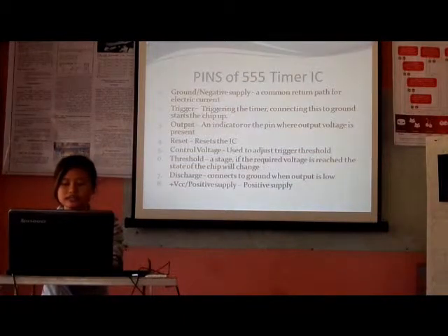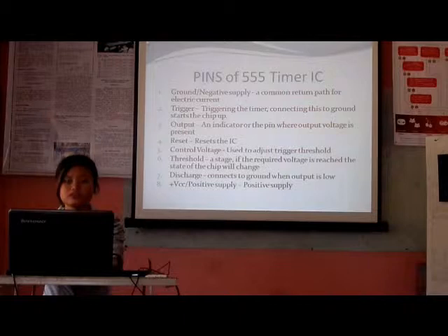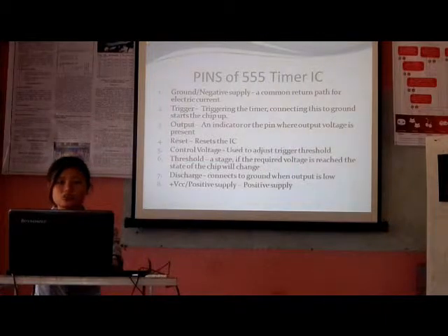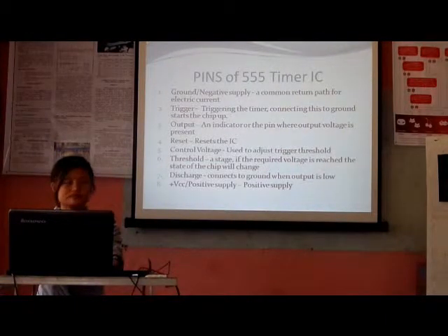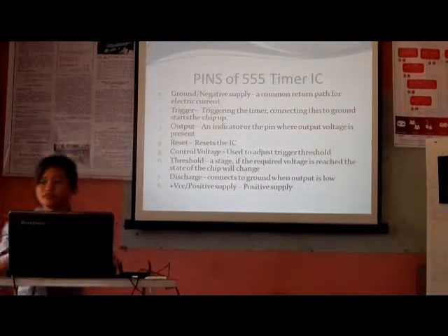The next pin of our 555 timer IC is called threshold. Threshold is the non-inverting input terminal of the comparator, which compares the voltage applied to this terminal with the reference voltage. The last 2 pins of our 555 timer are discussed to you by GP Villanueva, our co-teacher.